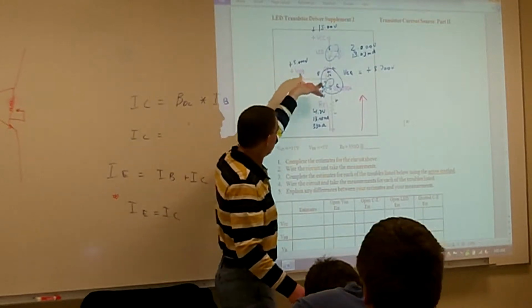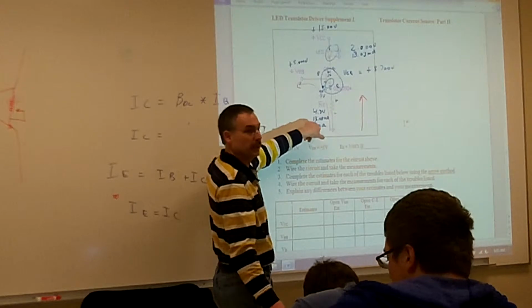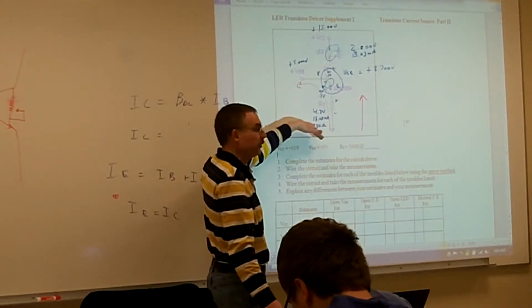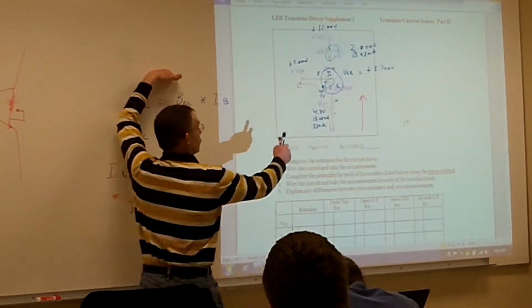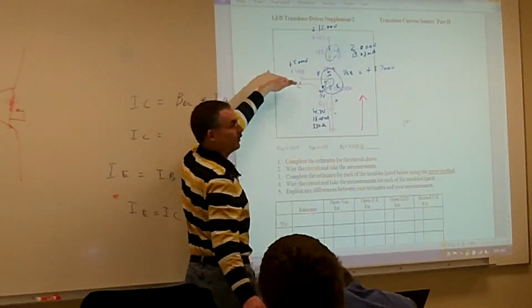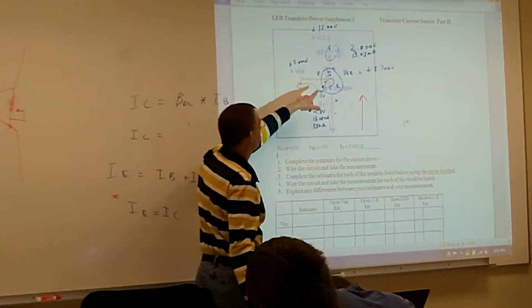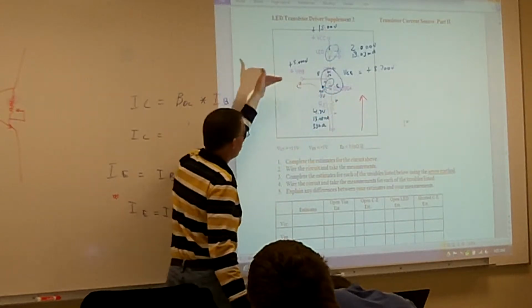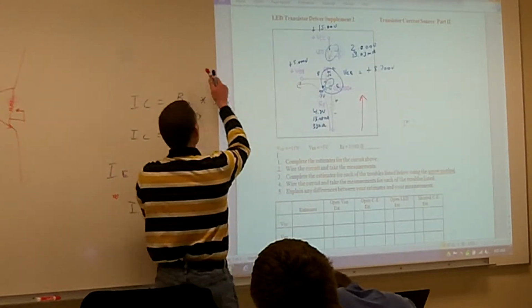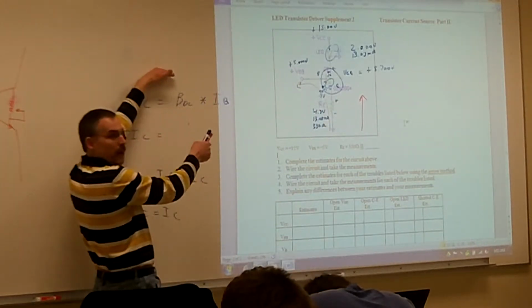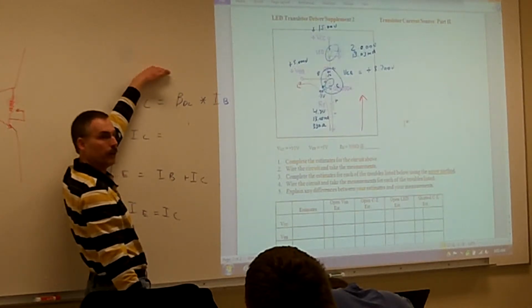My input resistance going into this thing is very small. It's going to be less than 330 ohms, or approximately 330 ohms. When this circuit's working normally, it's actually way up there in the mega ohms. Now all of a sudden this transistor failed, the input impedance dropped, the current started to increase across my base, and whatever this device is that it was trying to drive, we probably just burnt off this device because it couldn't handle that amount of current going through there.